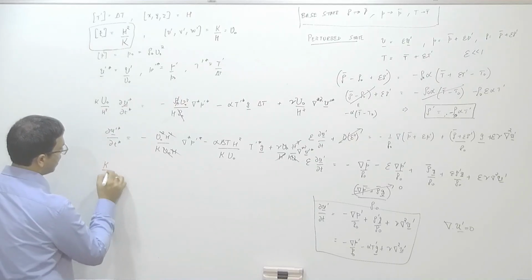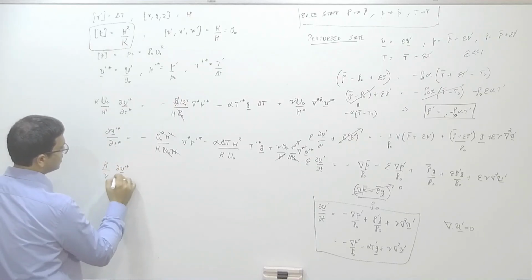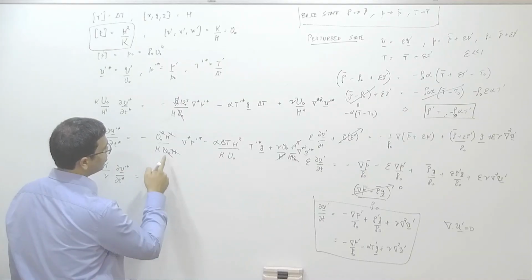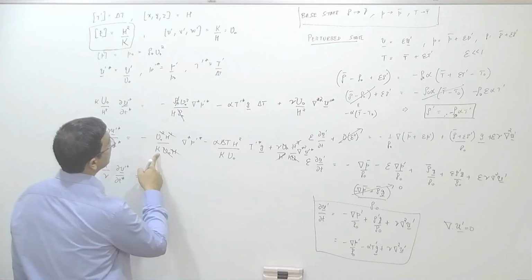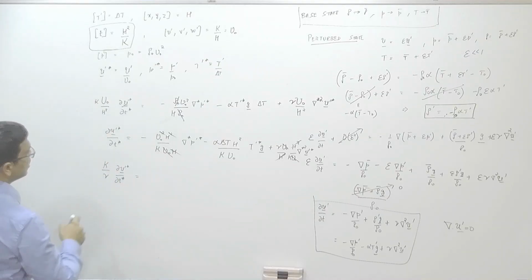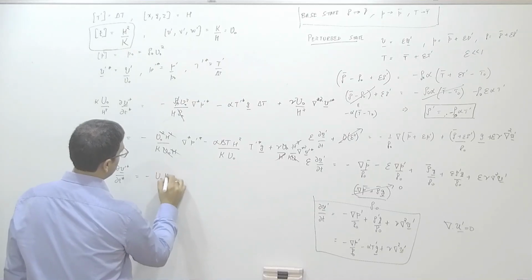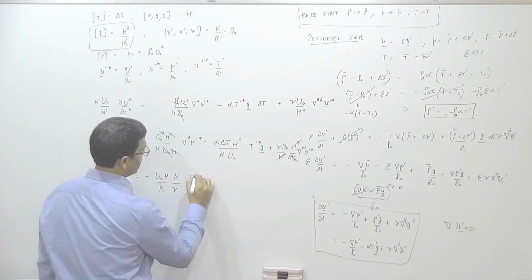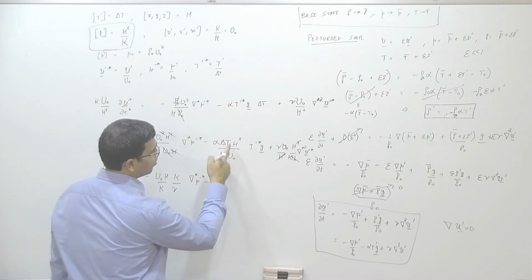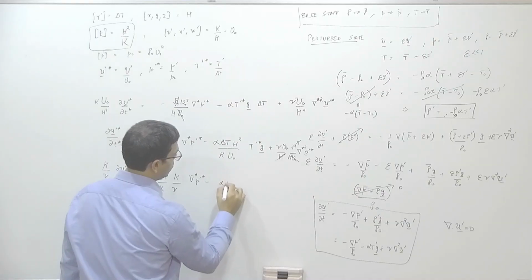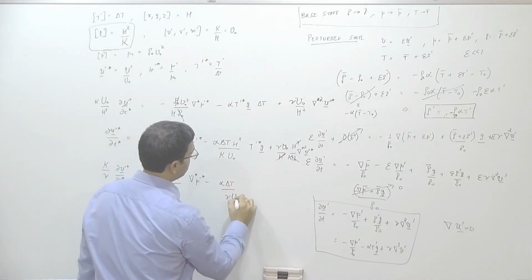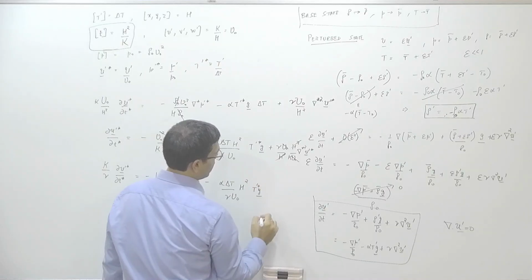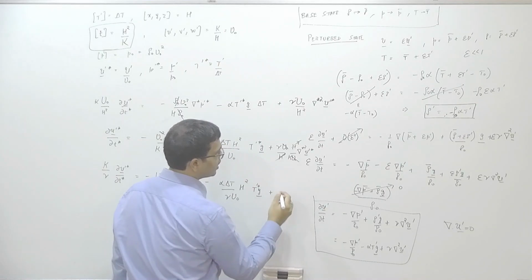So I'm going to write it as kappa over nu del u prime star over del t star equals, so here what do we get? A h by kappa, right? Did I miss anything else? Yeah, minus u naught h over kappa, and then I'm going to multiply by this del star p prime star. And now when I multiply here by kappa by nu, we'll get a very recognized number in these kind of problems, which are called natural convection problems basically.